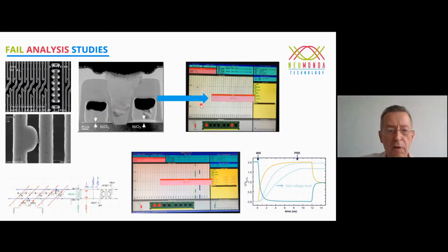You can do a lot of studies because our tester allows you to pull bit fail maps. This is a typical shared memory cell, the stack memory cell coming down. Then this here, then the selection transistor connecting it to the bit line. They share this contact. If a contact has issues, then typically those two cells fail. So you see a double fail here.